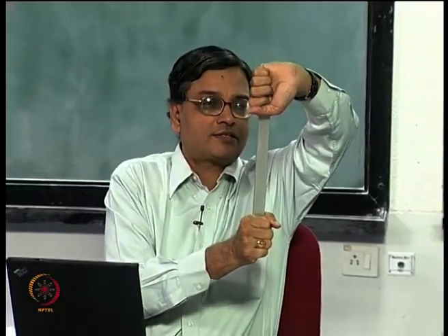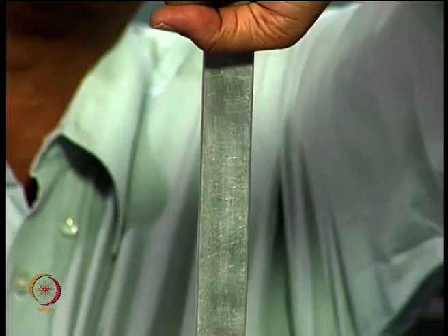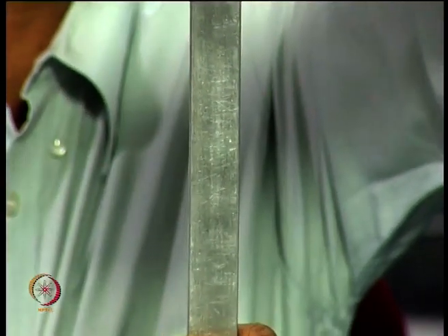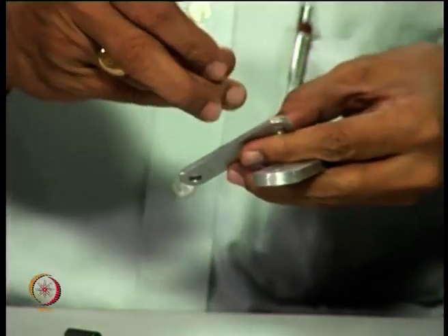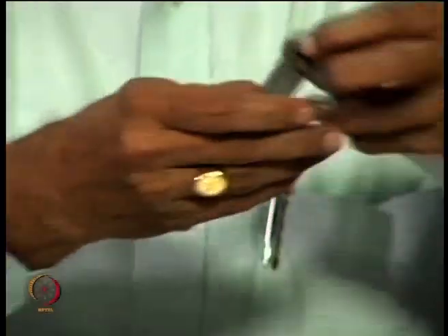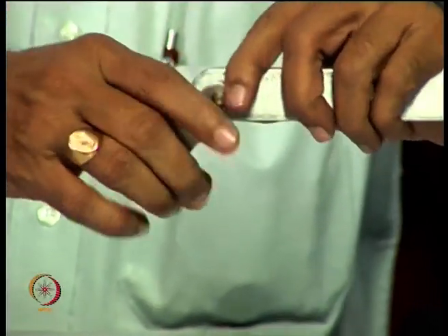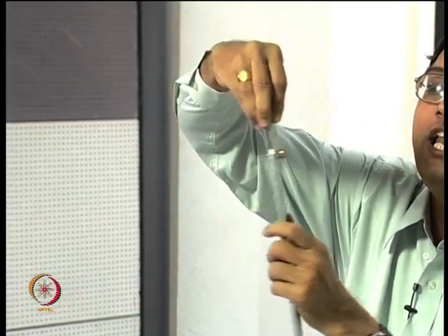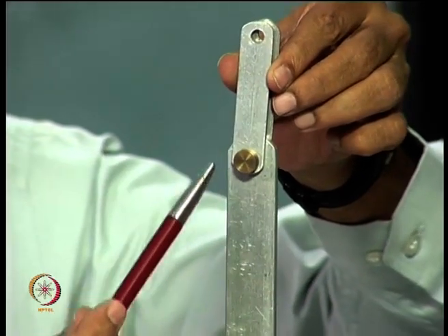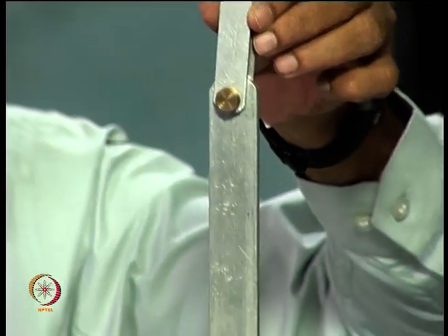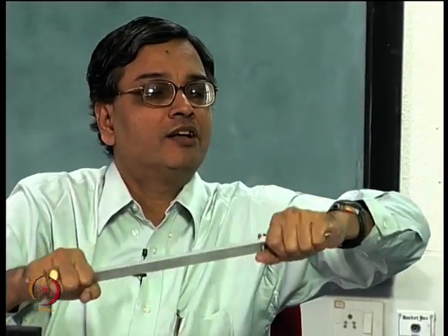Now, let us see one simple example. I have this rod and I want to pull it. I can pull it by grips. I can have solid grips and then pull the rod, and I can also pull the rod by another method, which is what you usually do. You have a sling and a pin, so you pull it with the pin. It also has a certain level of self alignment. If you look at the stress distribution in the close vicinity of the hole, and the way I grip it, these two are different, but our interest is to have an axial force in this member, which could be done in numerous ways. One way is putting a pin and sling and then pulling it, another is putting a grip. So, I am not really solving what I have in actual practice.